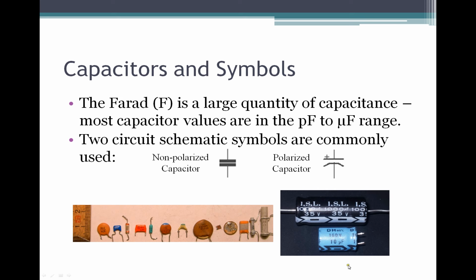However, because of this, we have to orient them a particular direction, and you can see here we have these arrows with these negative signs, and those negative signs and arrows point towards the low side lead of the polarized capacitor. Again, let me reiterate that in our analysis, it doesn't matter whether they're polarized or non-polarized capacitors. However, in actually implementing these devices, it is important to denote when we have a polarized capacitor which side has to be placed at the low potential side.